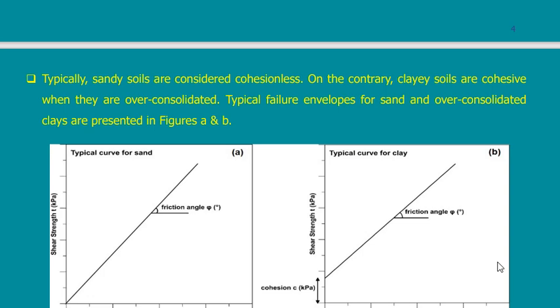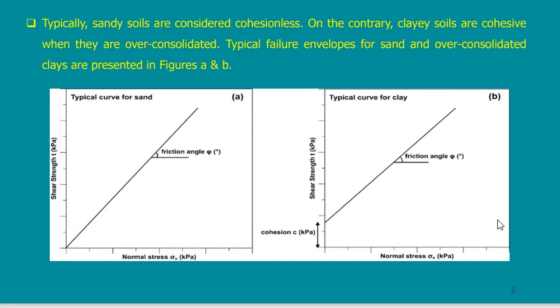These are the shapes for the test, because in some cases you may not get the value of the parameter, and instead you are given the name, pure sand or pure clay. Then you have to understand what this means. Pure clay, friction zero. If it is pure clay, then phi is equal to 0. No phi, it's just C. In this case, this will be the case. But usually, especially in clay, I will have some kind of phi.